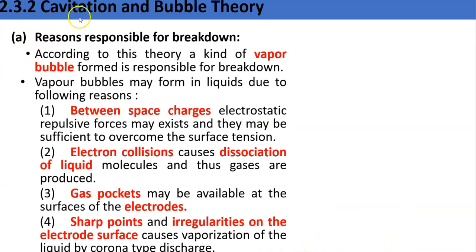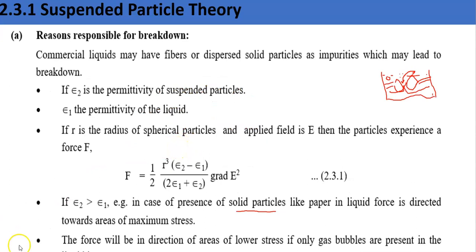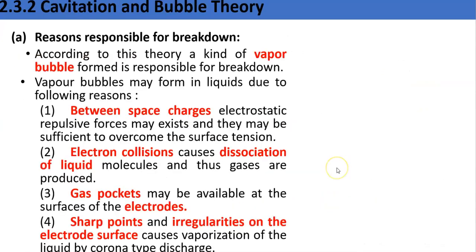Okay. So now what are the reasons responsible for breakdown? This is the cavitation and bubble theory. Suspended particle theory, have you understood? If not, then ask me the doubt. Now, in the second theory, cavitation and bubble theory, there is not much difference from the suspended particle theory. In suspended particle theory, we consider solid impurity. Here we will consider gas or bubble. So according to this theory, a kind of vapor bubble formation is responsible for the breakdown.